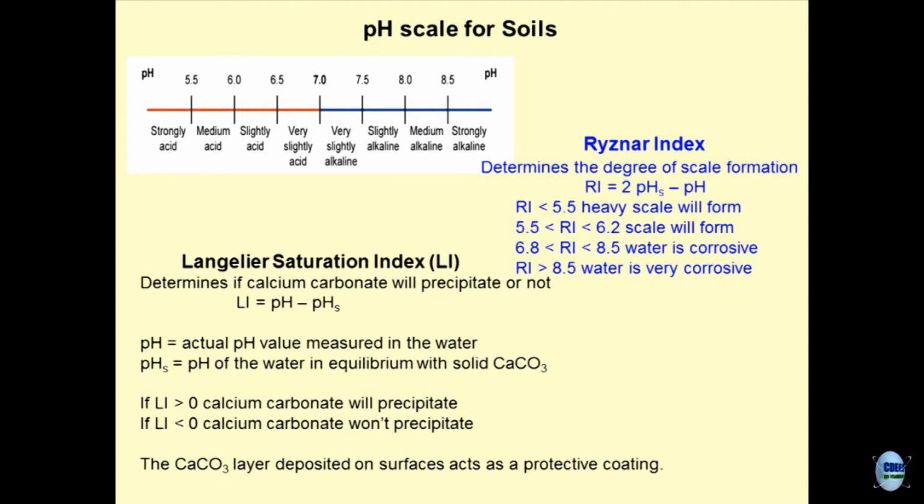So, how should I put this in practice? Give calcium supplement to the groundwater. How would you do that? I hope you are realizing the similarity between our profession and the medical professionals. Read more about the negatives of grouting. Gone are the days when people used to grout and put cement or calcium into the soils. Why? Because somewhere down the line it is going to create some imbalance.